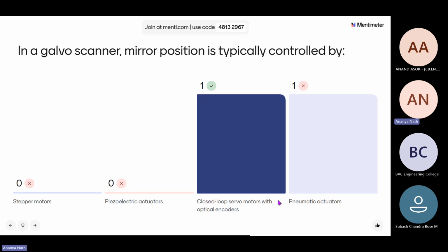They will be focusing the laser or the light, so they are very particular in focusing. Their resolution is very high, like the resolution will be sometimes in micrometer plus minus nanometer. So they are very sensitive products. If you're pairing it with a mechanical component to move them, then mechanical components will have some vibration that can destroy the resolution of the optical components. That's why this combination is not very good.